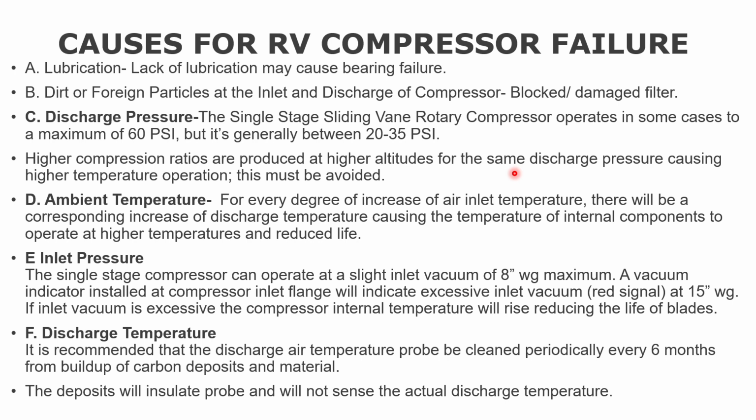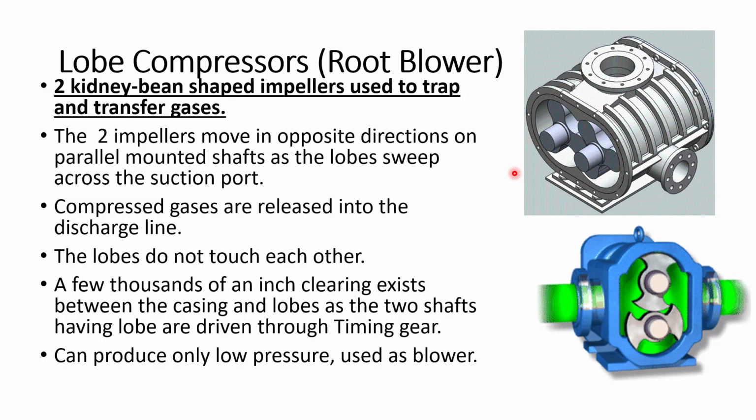Discharge temperature: it is recommended that the discharge air temperature probe be cleaned periodically, every 6 months, from buildup of carbon deposit and material. The deposit will insulate the probe and it will not show the actual discharge temperature.